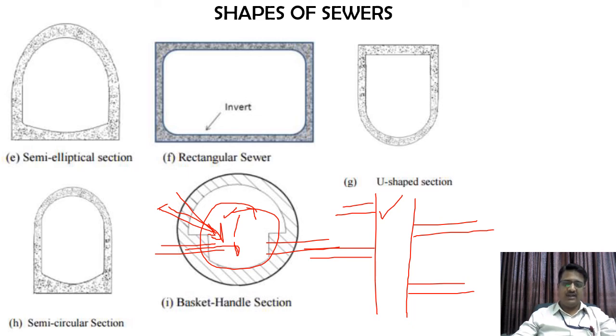So the only condition is that here we need to make sure that the entire system has a reduction in elevation, so that there will not be any clogging of these sewer lines, and also the smooth flow of that sewage because of gravity should continue over here.